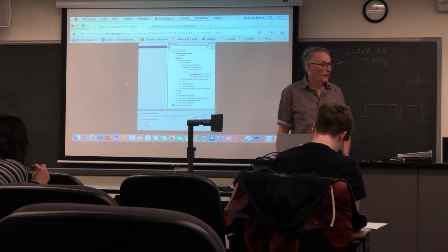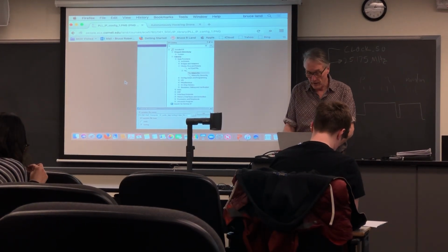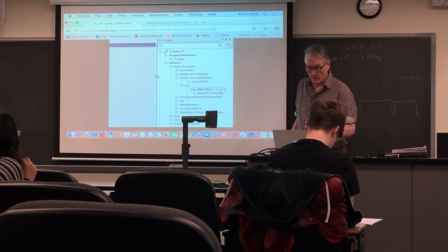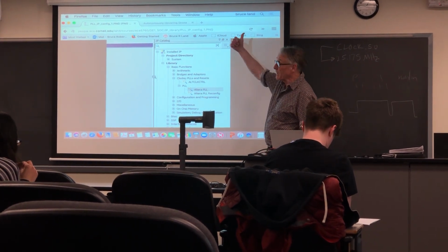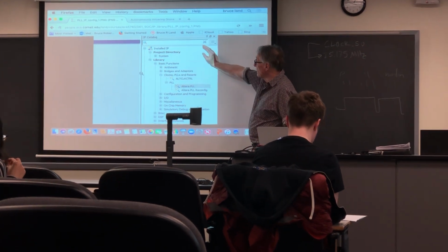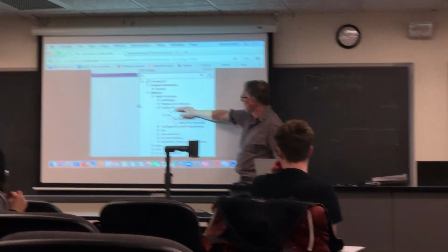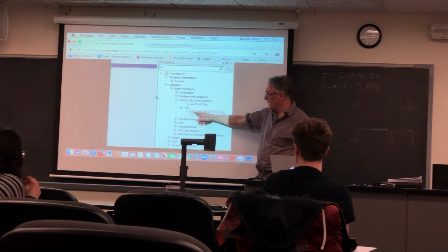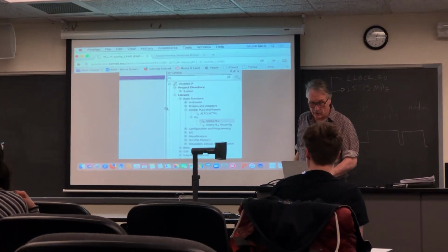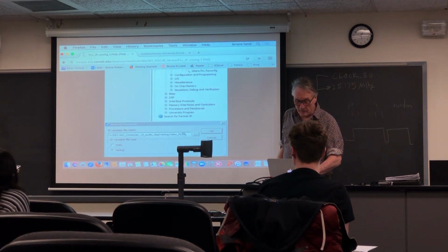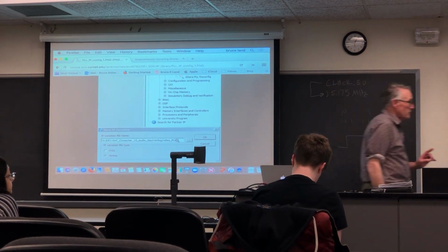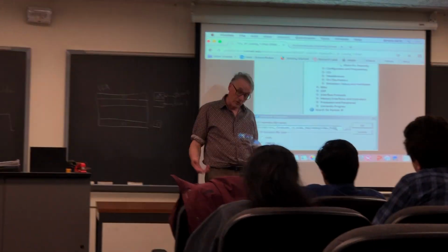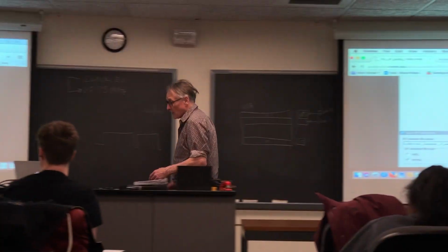First of all, you invoke the phase lock loop wizard, of course. In the upper right corner of the design area, there's an installed IP directory. Under basic functions, there's phase lock loop. You ask for the Altera phase lock loop, and it opens up a little dialog box in which you choose the name of the .v file that you want. I call this video_PLL.v.